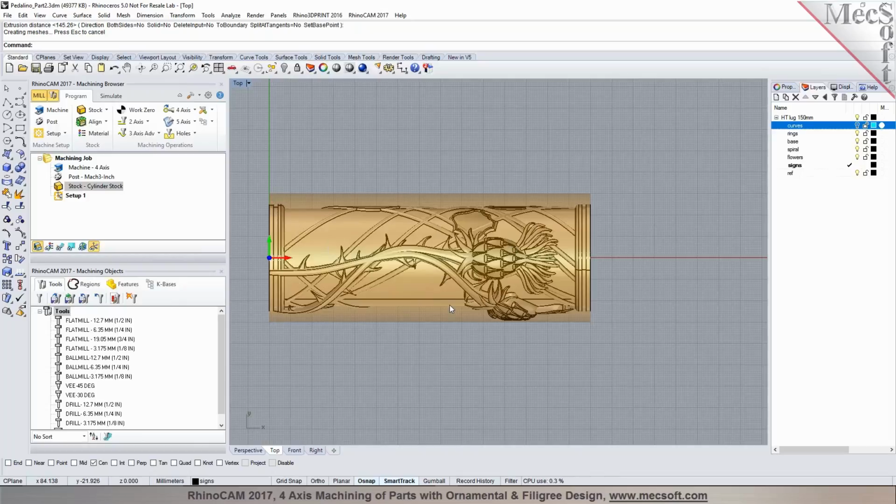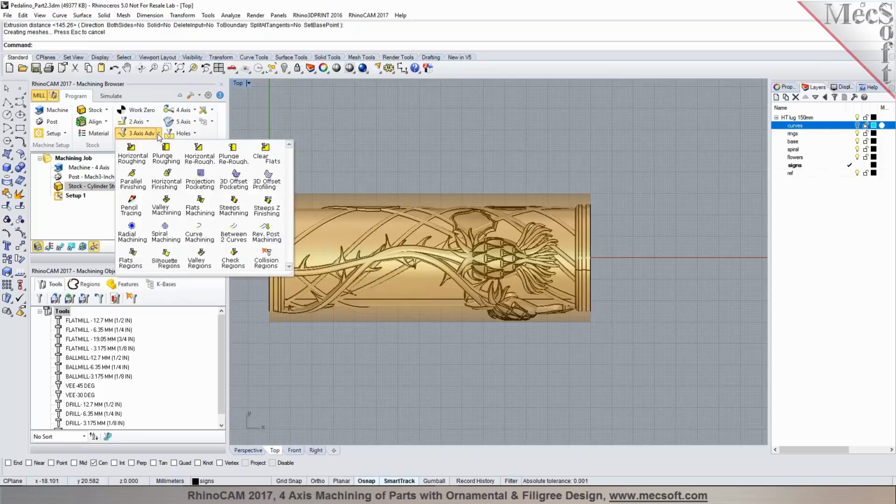So if you want to program this as roughing using 3-axis, you can then instance it for different orientations like 0, 90, 180, 270. That is index machining, where you lock the rotary table to different orientations. For that, we could go to 3-axis.